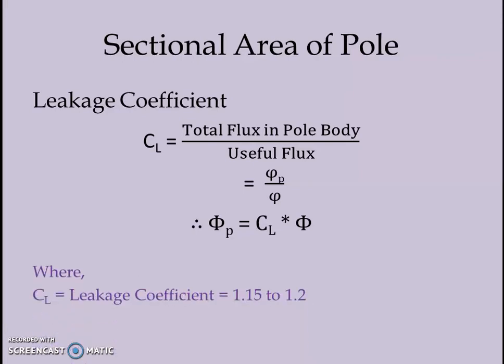An appropriate value of the leakage coefficient we need to define, and normally we take around 15 to 20% of the total flux. So that is 1.15 to 1.2 can be taken.